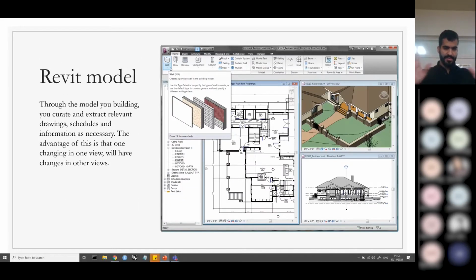Okay, so here's a snapshot of a Revit model. You can see on the top right is your 3-dimensional geometry preview, so your building, your landscape, your gates, windows, etc. And on the left, this is not a separate drawing, right? This is a drawing taken as a section from the model itself. So if you change anything in 3D or in plan, it updates in the 3D and section, etc. There's also the elevation. The elevation is taken from the 3D model. Everything's taken from the 3D model.